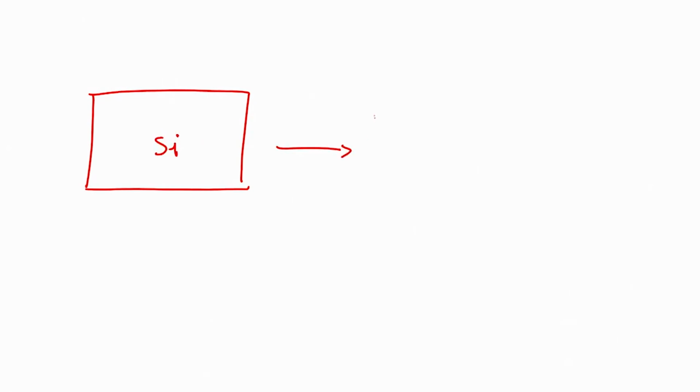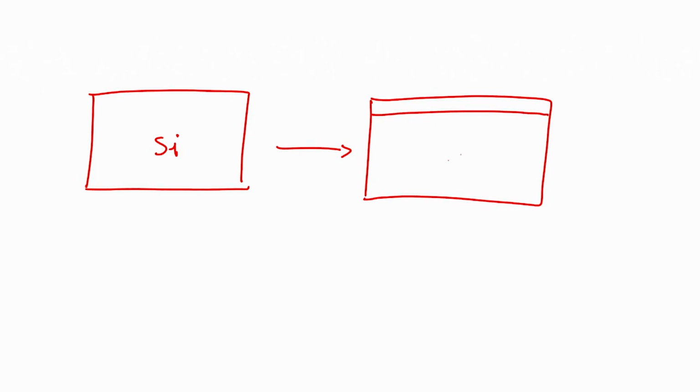First you have to deposit a metal, and the metal would be nichrome or platinum. If you see the screen, what we are talking about is if you take a silicon wafer. All of you are kind of experts in understanding the process flow, so I am not going into detail of the process flow, but if you have a silicon wafer and you oxidize it, then this is called an oxidized silicon wafer. This oxidation can be done using thermal oxidation, SiO2, this is silicon.